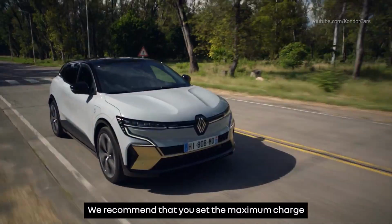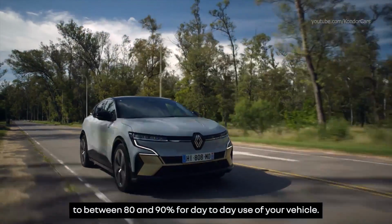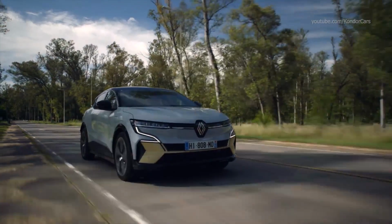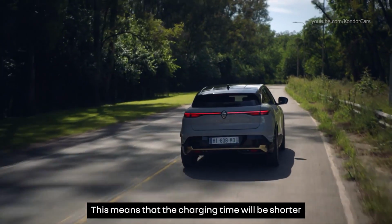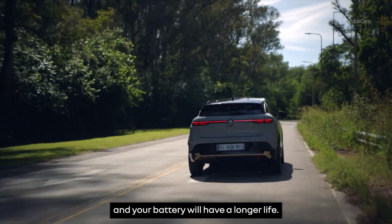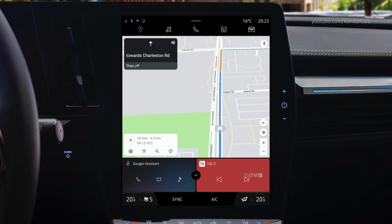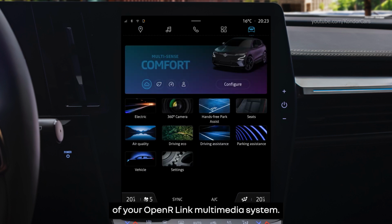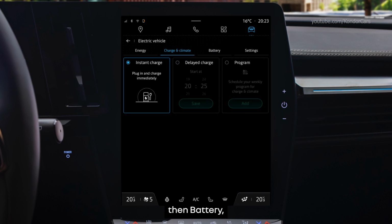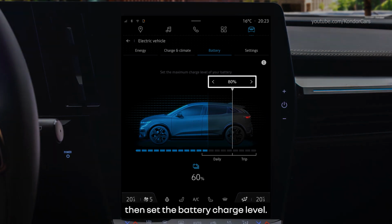We recommend that you set the maximum charge to between 80 and 90% for day-to-day use of your vehicle. This means that the charging time will be shorter and your battery will have a longer life. To do this, go to the Vehicle section of your OpenR-Link multimedia system. Select Electric, then Battery, then set the battery charge level.